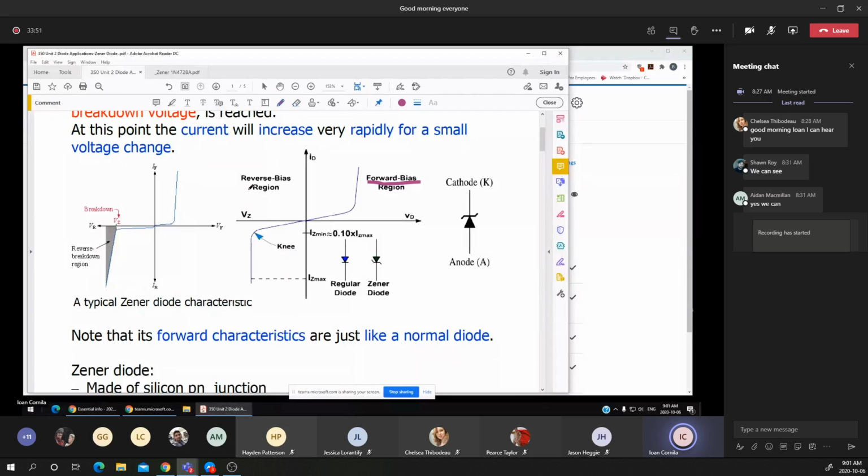Suppose that I'm choosing the VZ. If the supplied voltage is on the left side, or is greater than the VZ, the Zener diode is in on state, meaning that it will act as a Zener diode. It will regulate, or maintain, a constant voltage as the output voltage for the circuit.